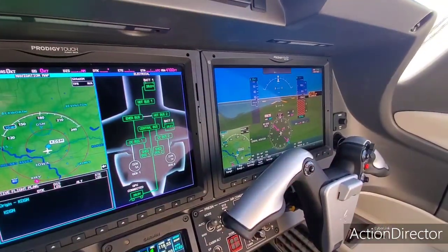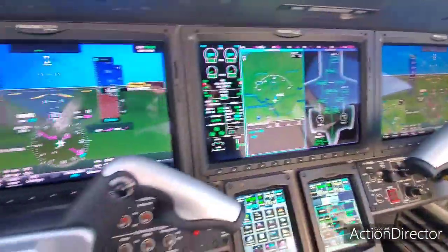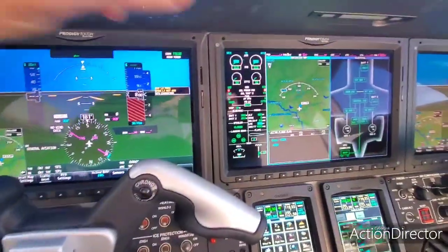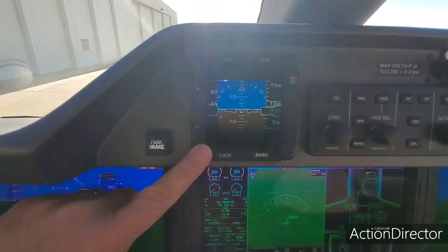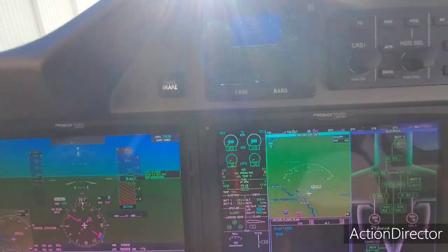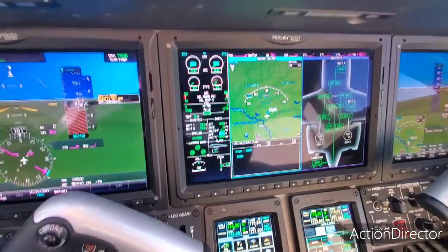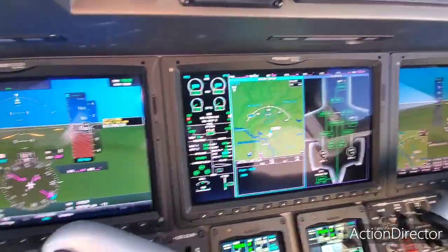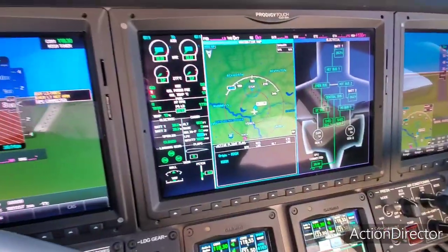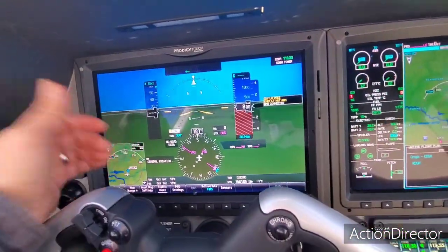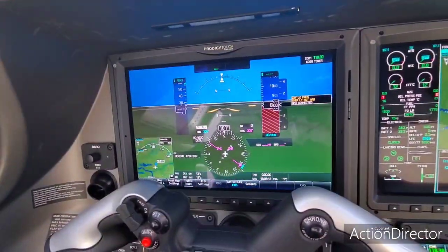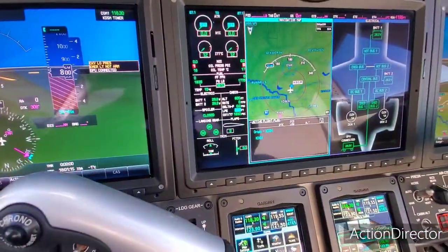So if these two are miscomparing, if the two pilot flight displays have different readings, we have a third on the standby flight. A third air data computer. So if we're in the clouds and we can't see, 2 beats 1. So you look for 2 agreement, 1 misagreement. And then we can also change the data sensor. Like if my air data computer goes bad, I can use number 2, but you don't want to switch till you know which one's bad.